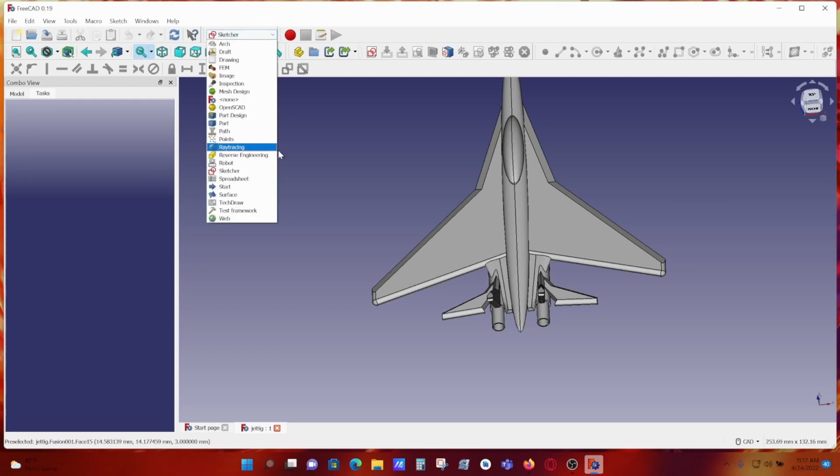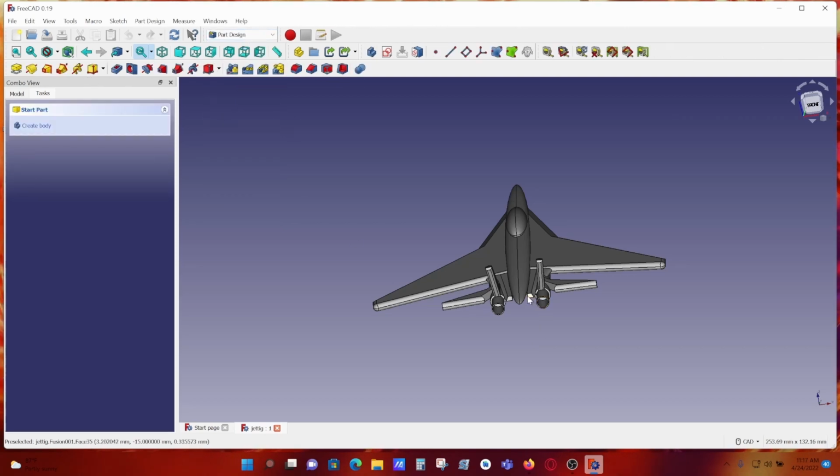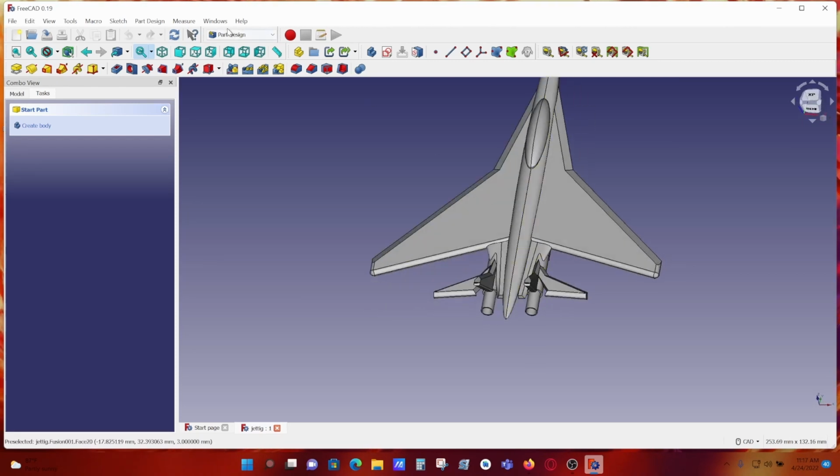The next part is behind the jet, the tail body of the jet. For that, I created two sketches, a quadrilateral and a curve, as you can see near the wings. And I used this additive loft to create a loft of the two sketches at two different planes to make this tail body. And those are all the parts.